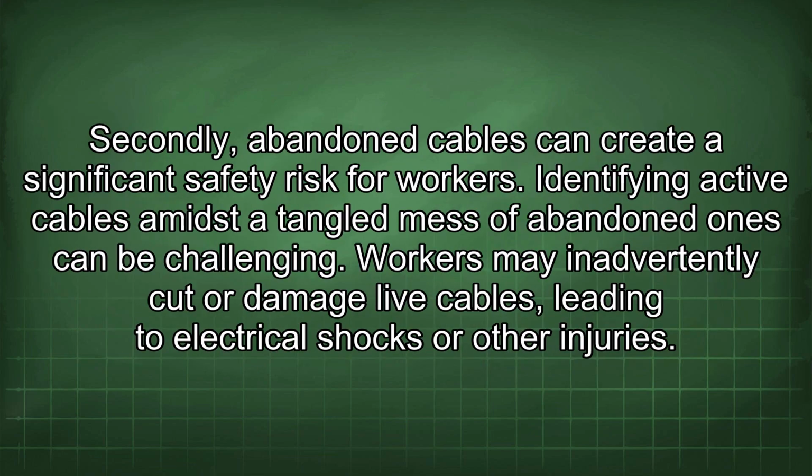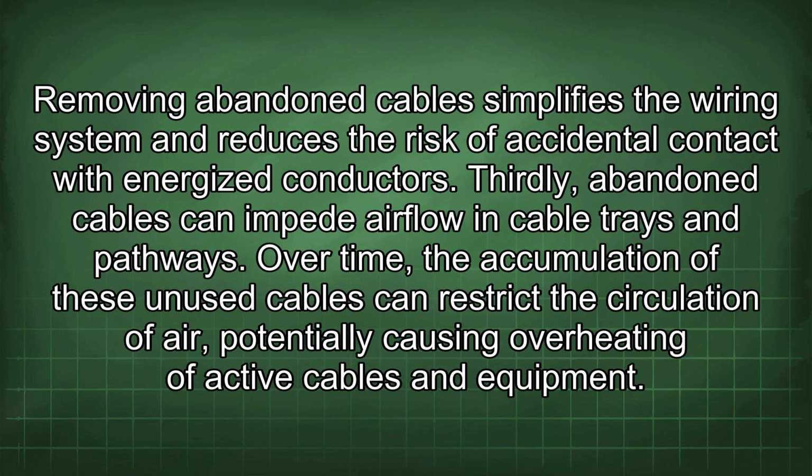Secondly, abandoned cables can create a significant safety risk for workers. Identifying active cables amidst a tangled mess of abandoned ones can be challenging. Workers may inadvertently cut or damage live cables, leading to electrical shocks or other injuries. Removing abandoned cables simplifies the wiring system and reduces the risk of accidental contact with energized conductors.